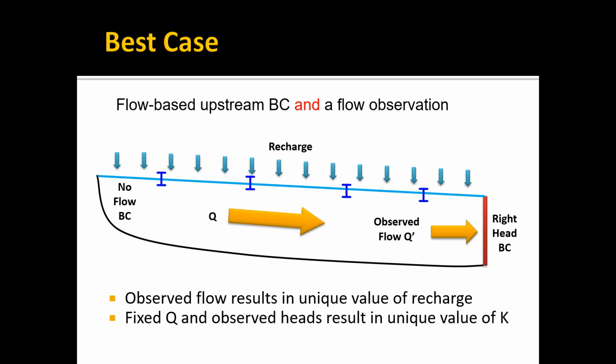Now, having said all that, the bottom line is you need to have either a measurement or some kind of estimate of the flow through your system, or your model's going to be pretty much worthless, because you could put any hydraulic conductivity in it and come up with any flow. As you change the hydraulic conductivity, it changes your flow rate proportionally. And we don't want non-unique models, because they become fairly worthless as a predictive tool.